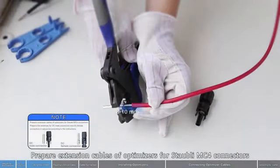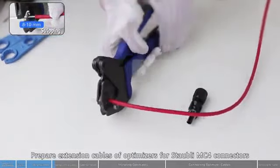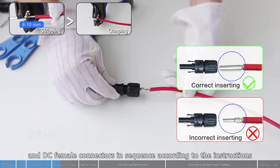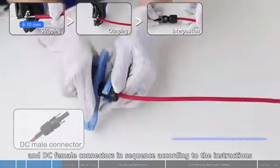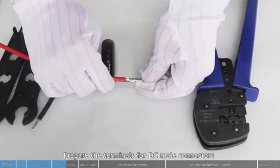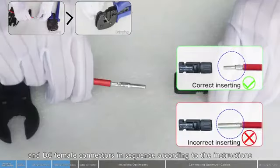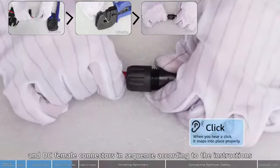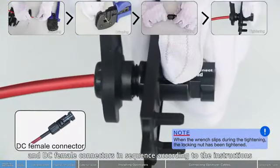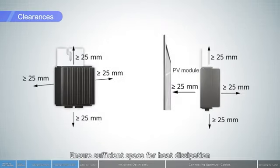Prepare extension cables of optimizers for MC4 connectors. Prepare the terminals for DC male connectors and DC female connectors in sequence, according to the instructions. Ensure sufficient space for heat dissipation.